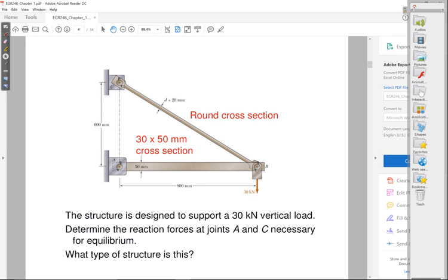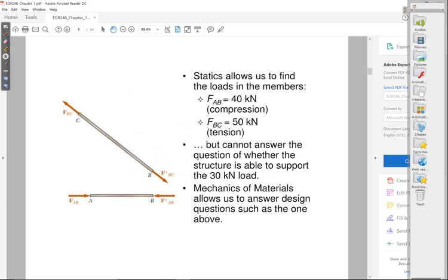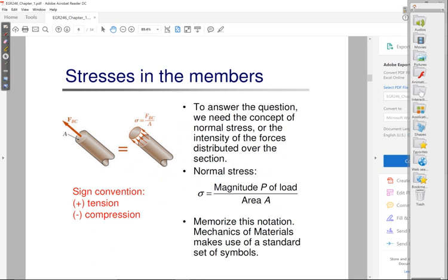All right, so how are we going to do that? How do we bring material into the design of these structures? In order to do that, we cannot rely on just looking at forces. We need something else. And what we're going to be using is referred to as a stress. By pure definition, this is just a definition that we've come up with. Stress, in particular what we call a normal stress, and I'll get into that in a minute, is defined as your internal force, we're going to call that P, capital P, divided by the cross-sectional area.